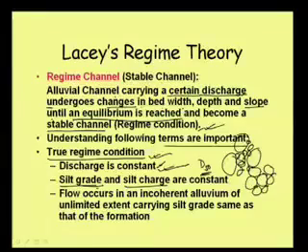That is, 50% of the silt will be finer than that size, and when 50% is finer, definitely 50% will be coarser than that. That is the definition we use for representing the silt size.